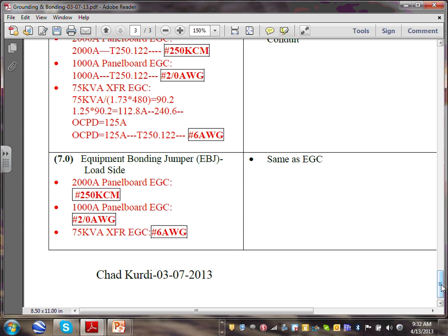So it's already oversized to cover the worst scenario, which is the 5000 amp. Now, if you go from each conduit, this is done. Here's to make it easy to understand. Okay, you have 5 sets. Do you have to form the same equipment ground conductor with every set? Yes. Because the code says, what if you have a short circuit in one conduit?